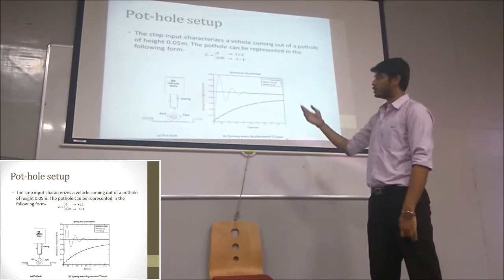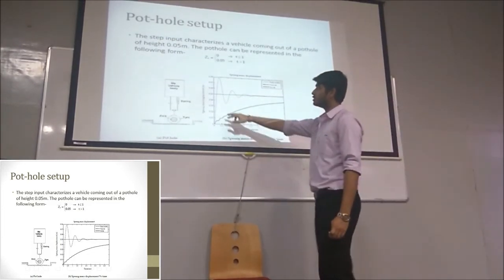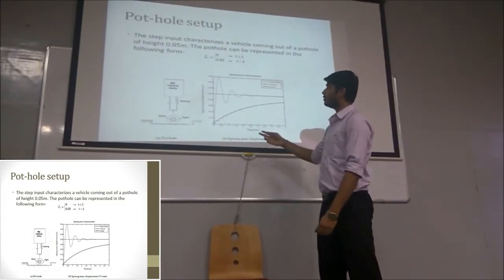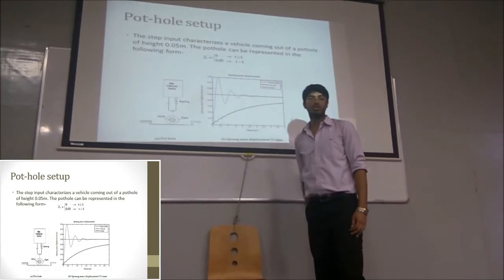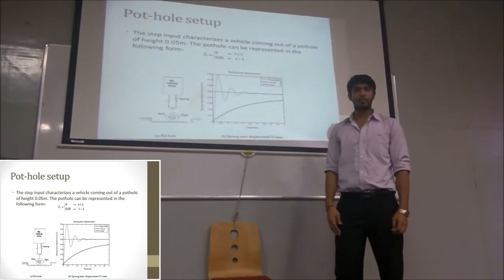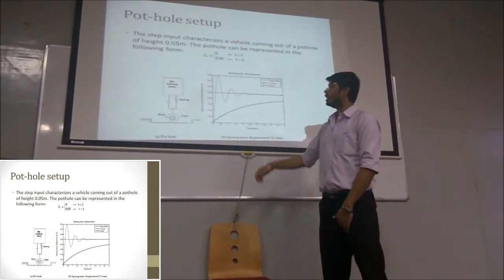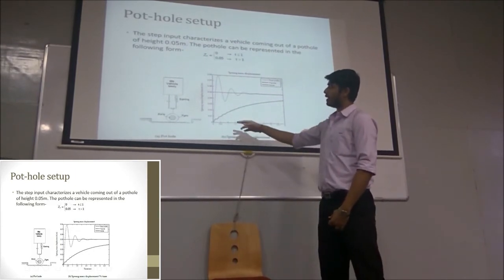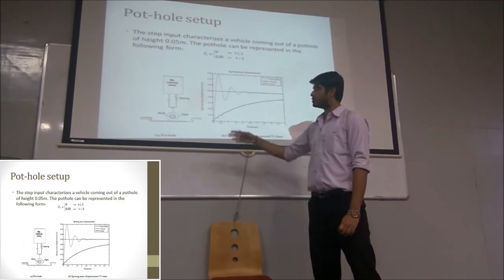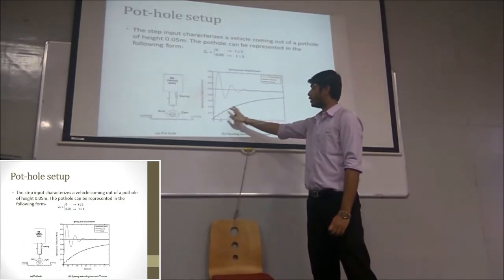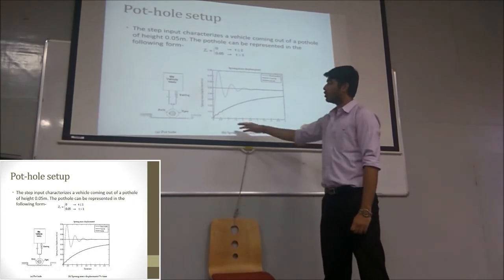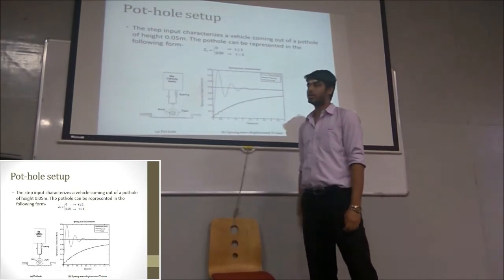with a displacement of 0.05 meters. The straight line in the graph shows the road profile for the time period, whereas the dotted line shows the performance of a passive suspension system in the pothole. It can be seen that the displacement that the passive suspension travels is quite high with respect to the active suspension system, wherein the active suspension system hardly goes to 0.01 meters.